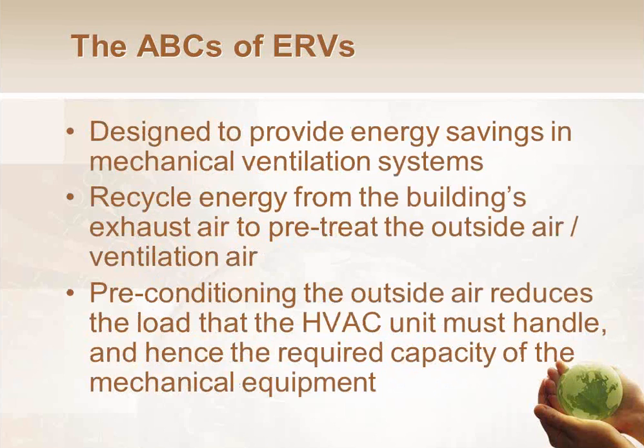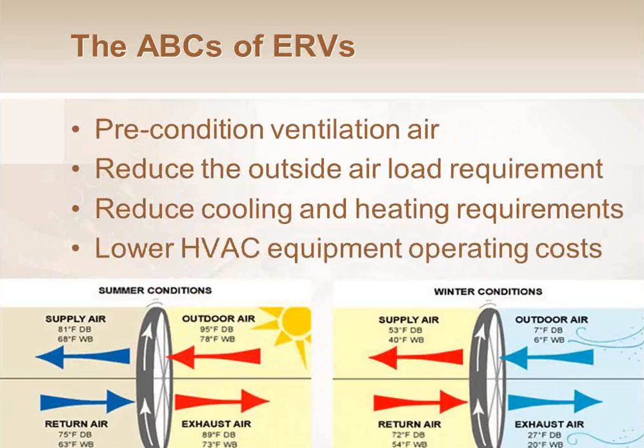The goal of this ERV is basically to take the exhaust air that we were going to throw out of the building and, instead of totally getting rid of it, recover the energy from that exhaust air. So not the actual air molecules or anything like that, just the energy in the air. Energy in our case today is going to be heating energy, cooling energy, humidification energy, and dehumidification energy. So we're going to grab that energy out of the exhaust air and transfer it over to the outside ventilation air that's coming in to preheat it, pre-cool it, pre-humidify it, or pre-dehumidify it, or some combination thereof.